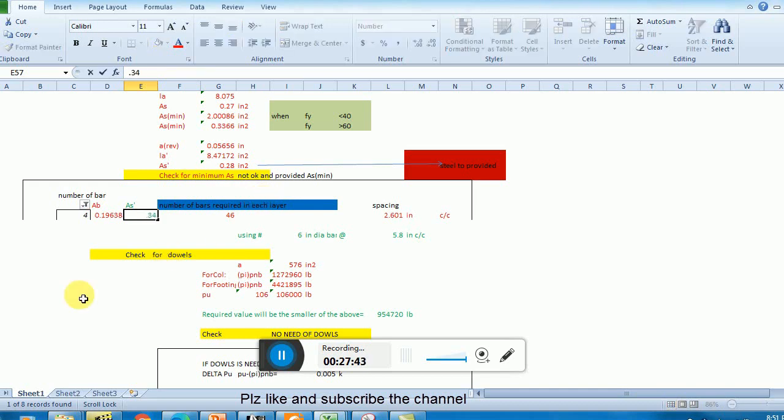Now we are using 0.34, that is my required area, and we don't care about this value, we don't calculate the number of bars, we are calculating the spacing of bars. I don't need this 10, so remove this one and check the calculation. So the spacing you need is 6.93.